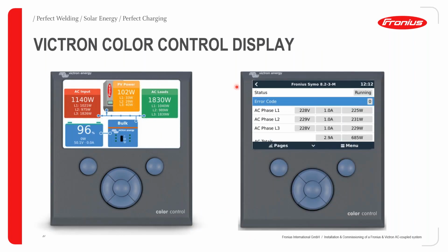So what I'm showing you is a screenshot of what a Fronius Victron system can look like. In this case, we have a cloud control. And here you can see we have your Fronius system, which appears. And here you can see your PV generation. You can see your AC loads. You can see the state of charge of your battery. You can also see your different phase currents, etc.